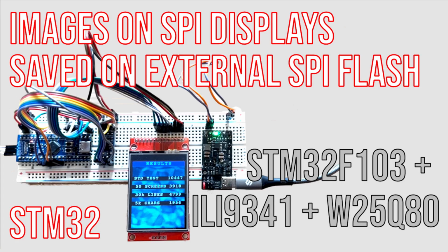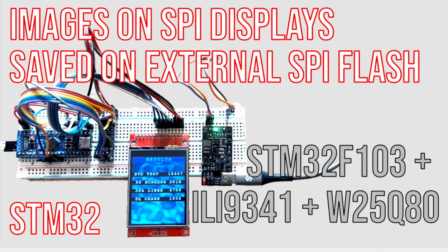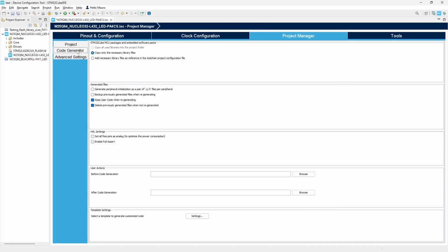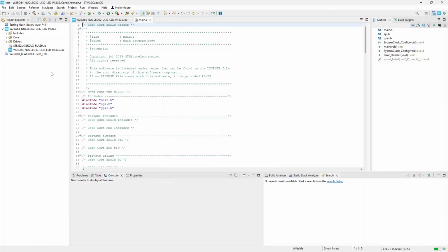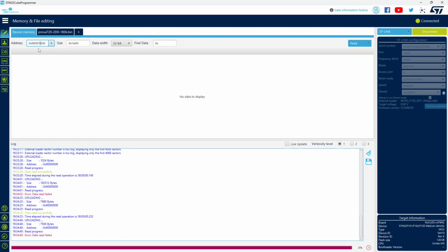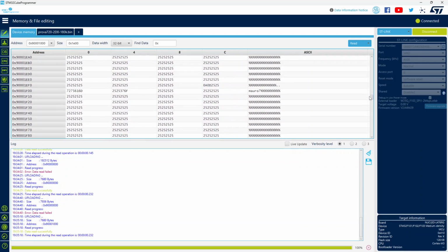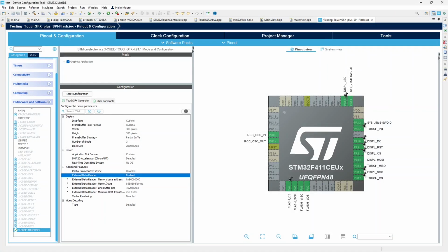Is it possible to make an SPI Flash memory transparent to a project? I mean, we have seen in other videos how to use a W25Q flash memory connected to the microcontroller having a single SPI port, and how to create an external loader handling it. We have seen also that, using an external loader, CubeProgrammer handles an SPI Flash having it mapped on the microcontroller address space. A TouchGFX project also uses a mapped SPI Flash memory with the help of an external loader.